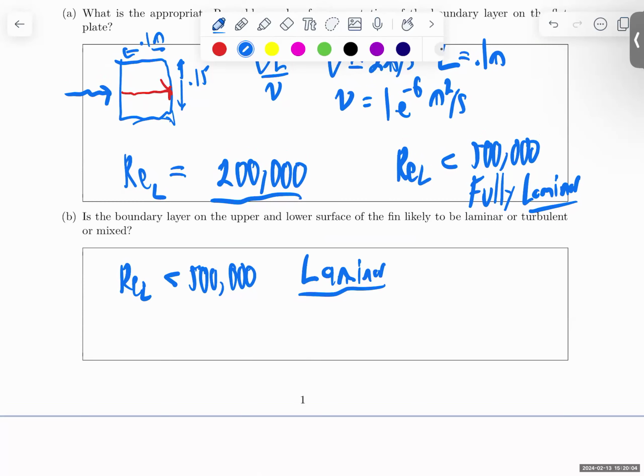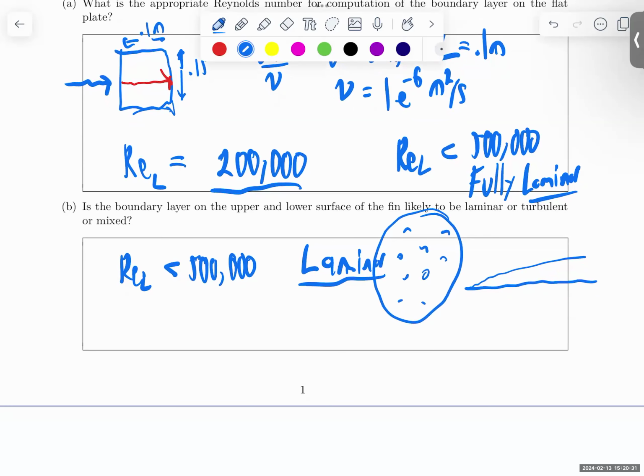The other thing it depends on is the boundary layer. Like I'm drawing a side view again, there's the boundary layer forming. The flow itself, we've been drawing it as having perfectly beautiful uniform flow, but the reality of the ocean is not perfectly uniform. There's lots of little turbulent eddies all the time in the free stream flow. We refer to this as free stream turbulence, little eddies that exist all the time because nothing is clean about the ocean water. And so the level of this free stream turbulence can impact the transition from laminar to turbulent. So those are the two key things it depends on.